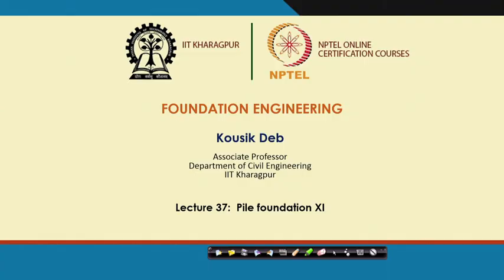So, last class I discussed the calculation of load carrying capacity of pile by using dynamic equations. Now I will explain the fourth method by which we can determine the load carrying capacity of the pile, and that is based on the penetration data. Penetration means SPT or the CPT data.